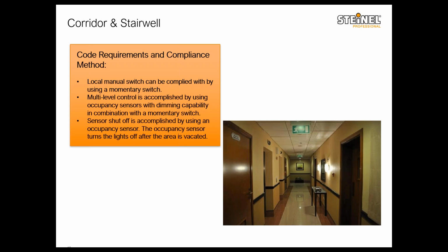So the lights won't be turned off completely at all. So you still need your manual override switch, which in these cases should be blocked from unauthorized access. You have your dimming function, and the dimming sensor should be set to partial off. So there would always be some lighting in the areas of egress, for safety reasons.